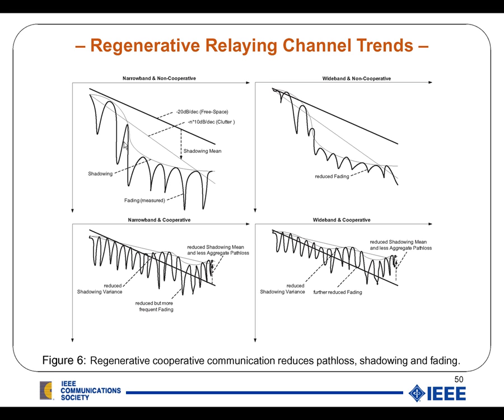The shadowing process also depends on distance, depends on cell size, it depends on the environment, where typical values range between 2 and 16 dB. And then you got the small scale fading, which is seen here, and that is the actual fading which is measured by my terminal.